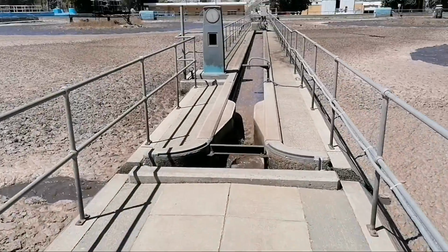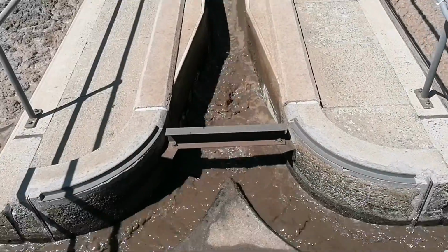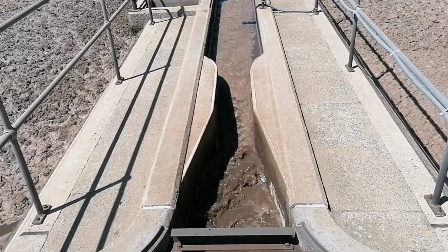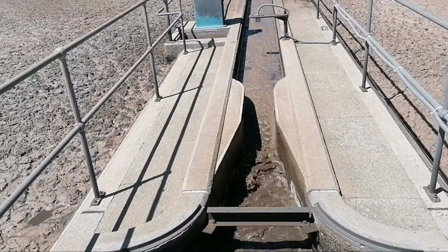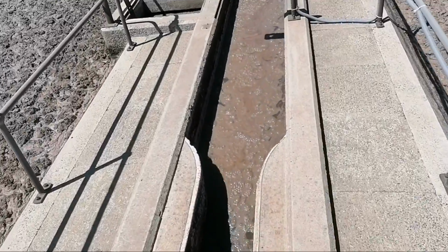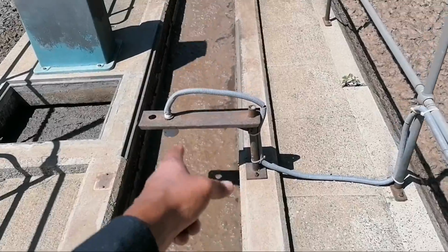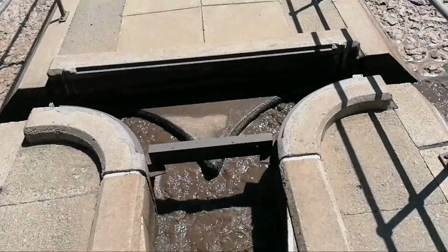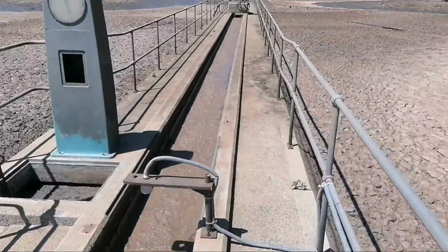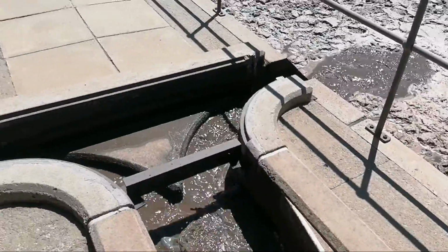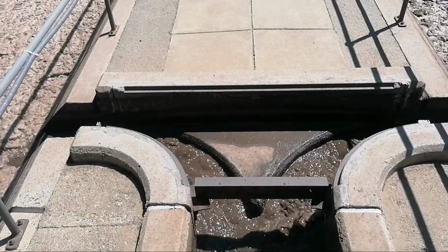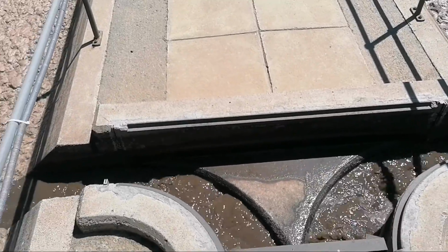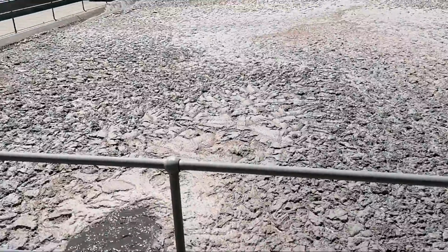Okay. Now we are seeing aeration 1. There is return water also coming to aeration 1. You can see some water is given back to the aeration tank for a good biological process. Here there is a flow meter again, to measure how much return water is coming to this aeration tank to improve the biological process. The return water comes and it is divided into 2. One is going to the right side segment and one is going to the left side segment. You can see here clearly, so that the biological process will improve.